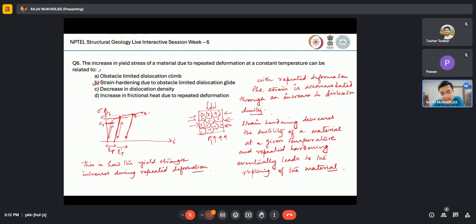Long range elastic interactions mean the repulsion between the dislocations can send them apart by a characteristic length scale that is much larger than the grain size itself. That is the long range elastic interaction. It's taking place over a longer range.